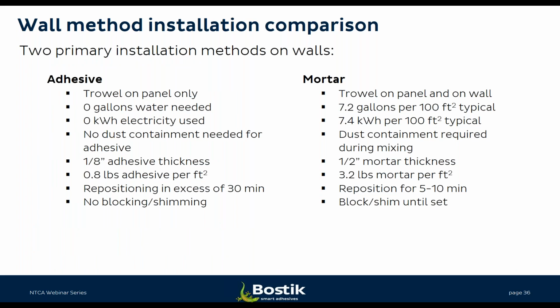So these particular materials and methods allow for a little bit faster of a turnaround, both on the staging aspect as well as on the application standpoint. From an application, it's troweling only half of the material, so it's only troweling onto the back of the panel as opposed to having to trowel on the back of the panel and the wall. So there ends up being a time savings there against a traditional mortar installation, as opposed to what you'll see with doing mortar on a wall surface as well.